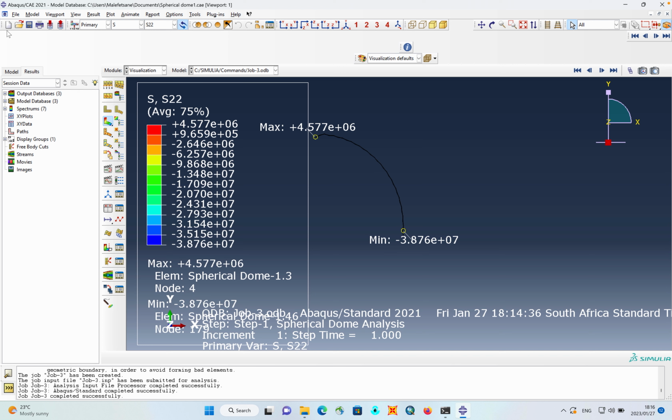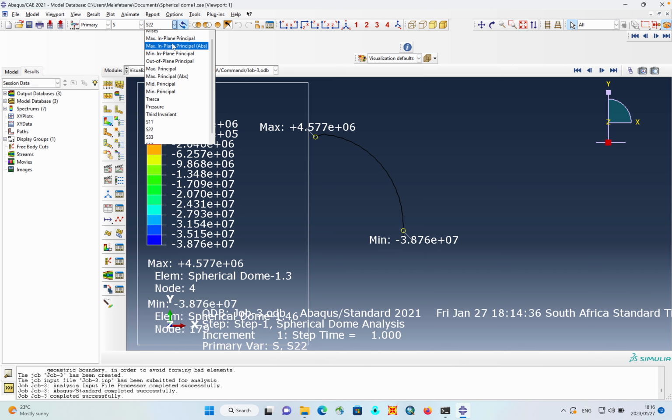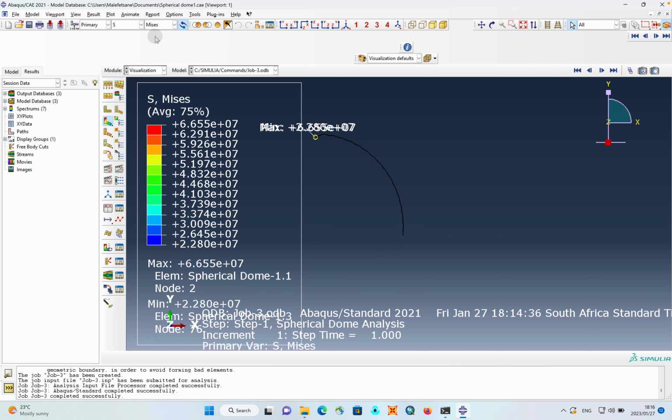Okay, so pascals in terms of megapascals, because you want megapascals, it's going to be to the -6. So basically here what you're seeing is 4.6 megapascals, but remember we are looking for what? We are looking for 50 megapascals, if you remember in our problem. Okay, but now what is the stress that we're looking at? First, this is the von Mises stress.